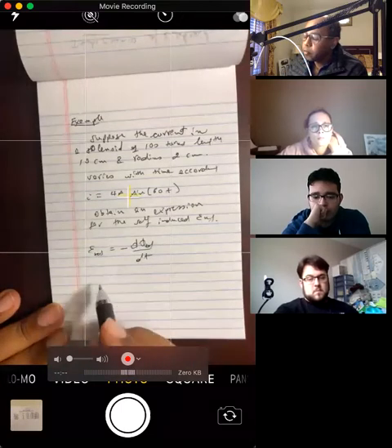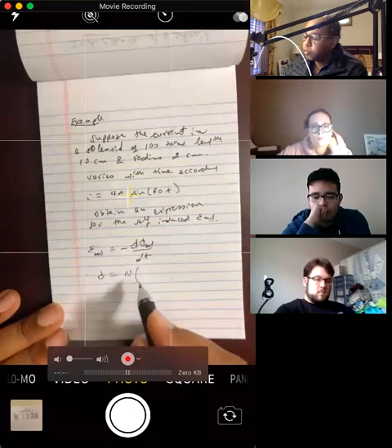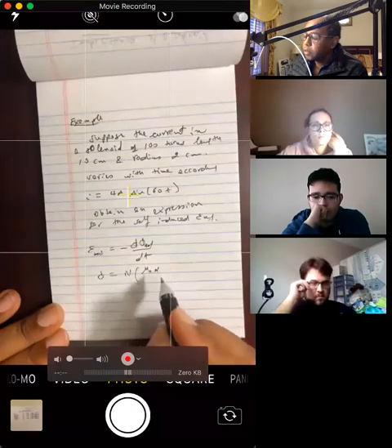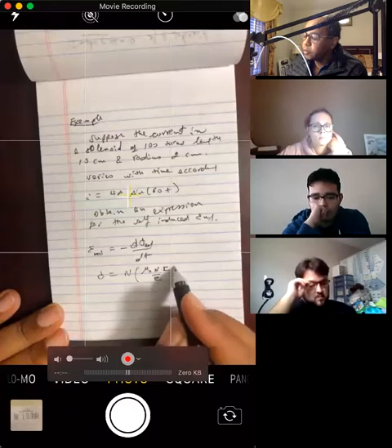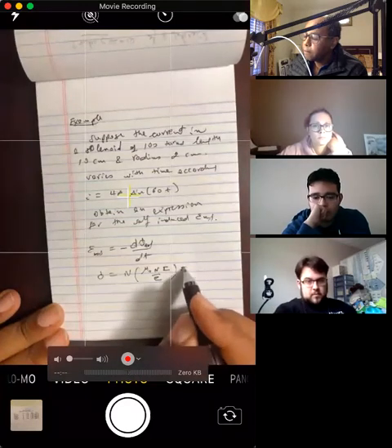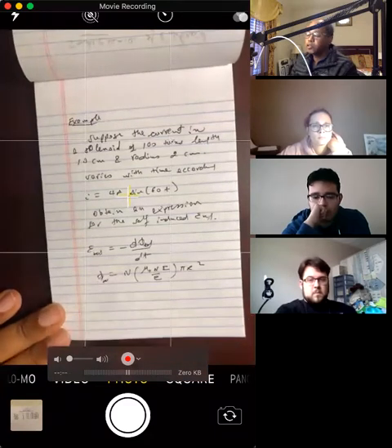And the flux, of course, is the number of turns times the magnetic field, which is mu naught N I divided by L, that's the magnetic field. And then you've got the area, pi r squared, okay? This is the self-induced flux.